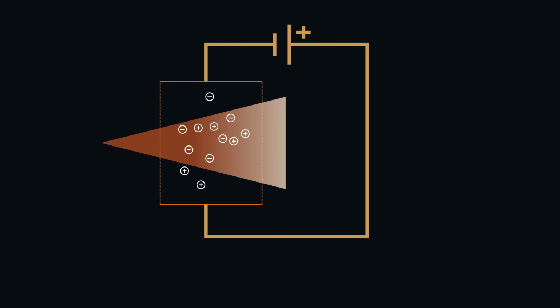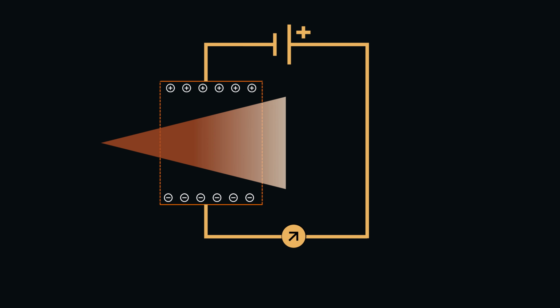Now imagine two plates with applied voltage are surrounding the air volume. The produced ions, electron and the positive remaining of the atoms, will be attracted to the plates. The electrons, negative charged particles, will be attracted to the positive charged plate, while the positive ions will be attracted to the negative charged plate. This ion's movement will induce current that can be measured by an electrometer.